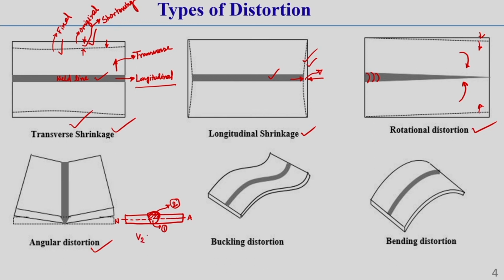Now, once this material solidifies, the loss of volume of molten material, or you can say weld material loss, is higher generally on the top side, and this will create some shrinkage force. So, shrinkage force you can say is proportional to the volume of material solidification. What I am telling, understand? So, the higher the volume of material solidification, the higher will be the shrinkage force.